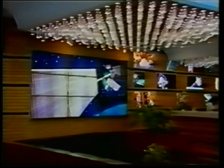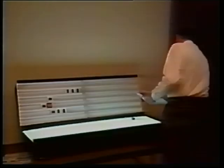So far, we've explored the basic concept of fluorescent lighting, as well as some of the varieties and styles available. Compared to an incandescent lamp, a fluorescent lamp has a very long life. In fact, the average life of fluorescent lamps can range from 6,000 to over 20,000 hours. The life of a fluorescent lamp is usually determined by the number of starts, that is, by how many times it is turned on and off.